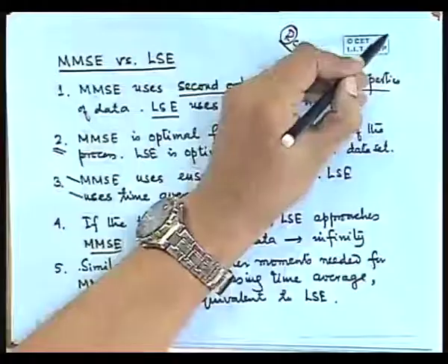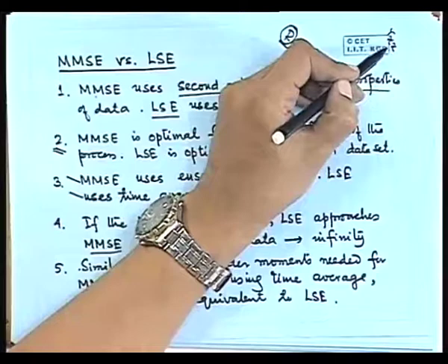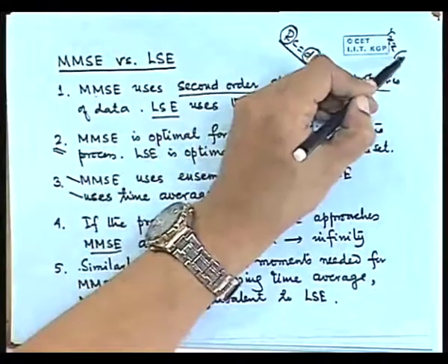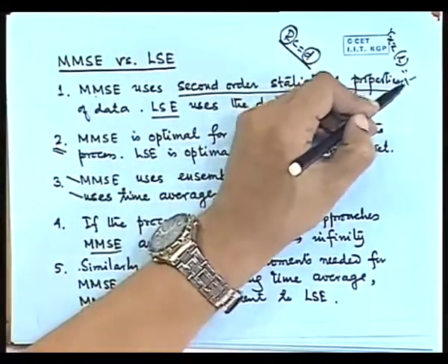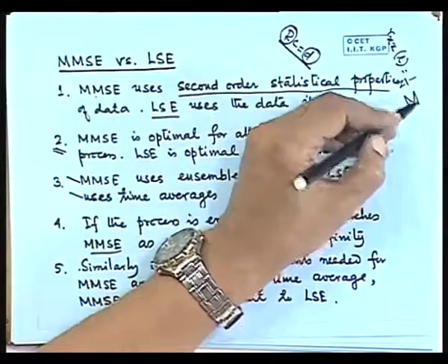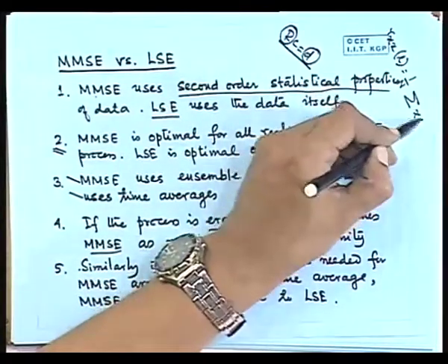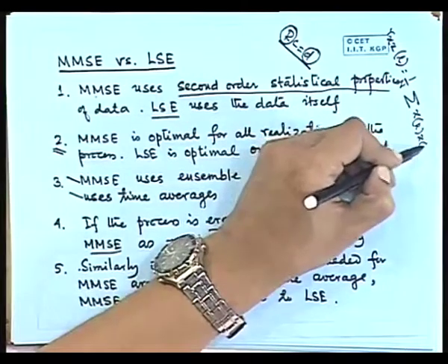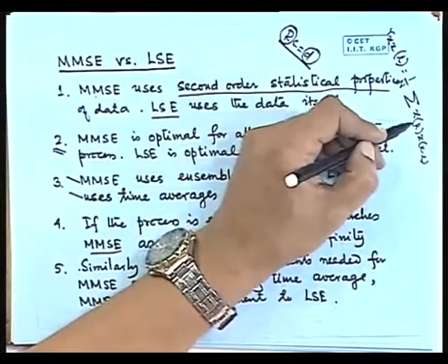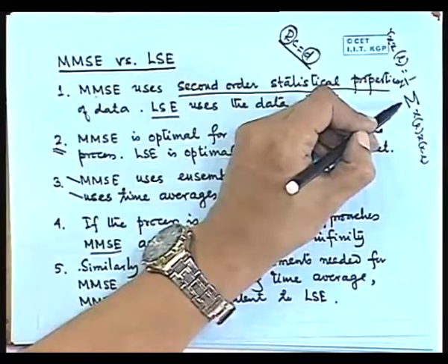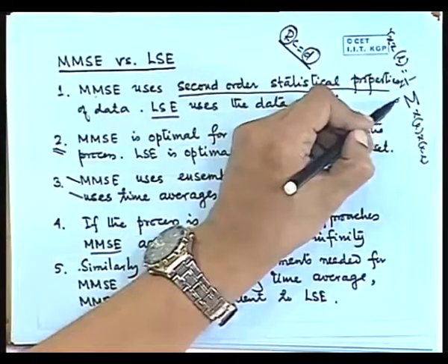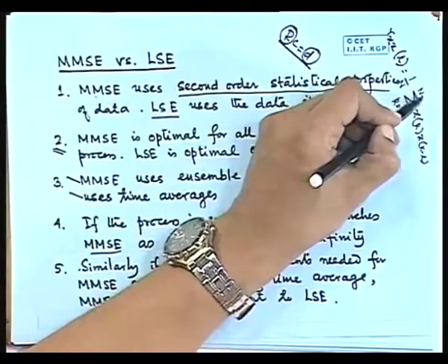But remember that what we said is that if you are given one sequence, how can you estimate the autocorrelation function? So we wrote that it is Rxx. Can you see this on the screen? So you saw Rxx(l) is equal to 1 by N sigma x(k) x(k minus l), where k will go from l to N minus 1.